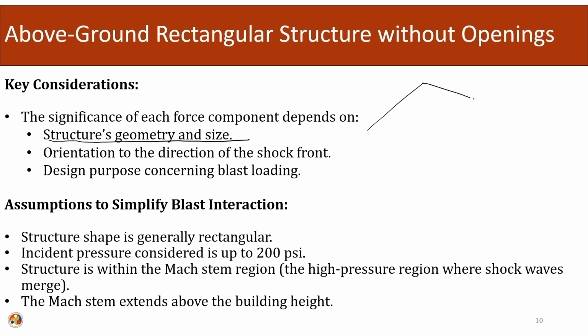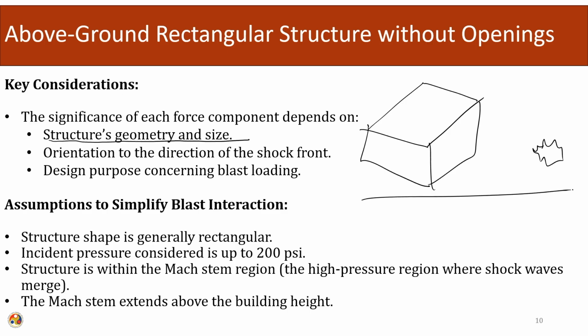We will have to account for the geometry, rectangular, triangular, similar, and the size of the structure with respect to the location of the blast. This will determine whether we are having a planar front, or whether the pressure is changing as the length of the structure increases.